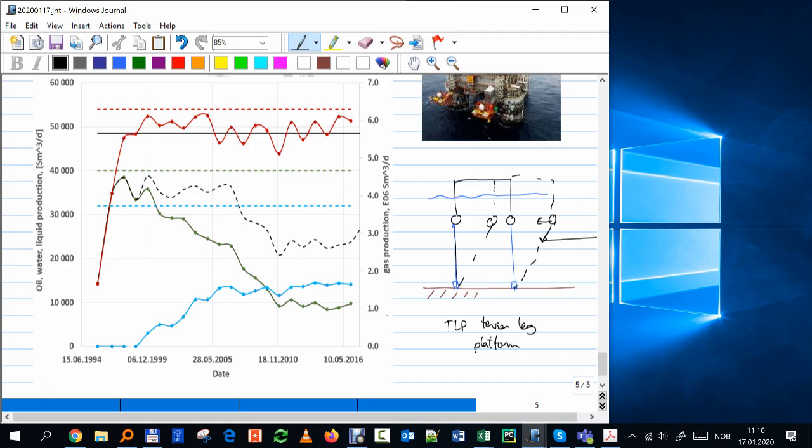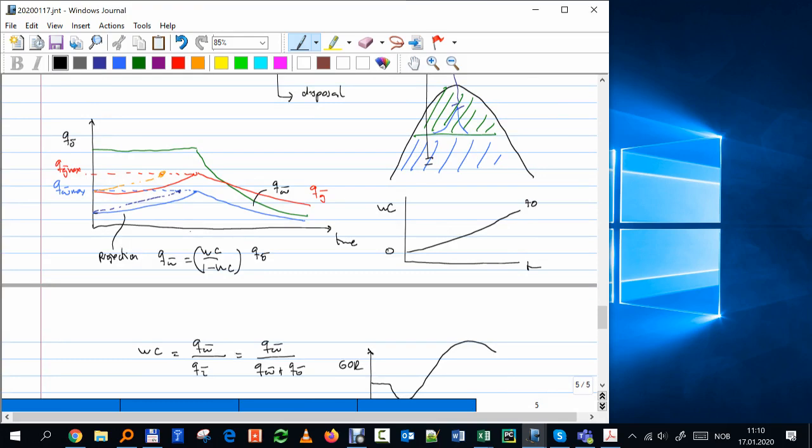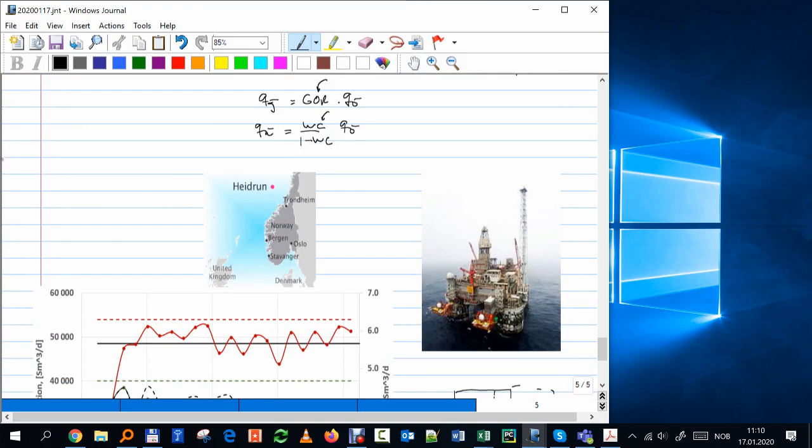What I see in the plot is that it's almost at the same time as the decline in the oil phase started. So when I see this plot, I can arrive at the conclusion, because I don't have any other information, I don't work in Equinor, I don't know what happened, but I might say they had a problem with early gas breakthrough. That caused them to reduce the oil rate because they cannot process more gas. Of course, the real data doesn't look so nice as that plot. It's not a continuous line, it has a lot of ups and downs, but actually it's trying to send you the same message.